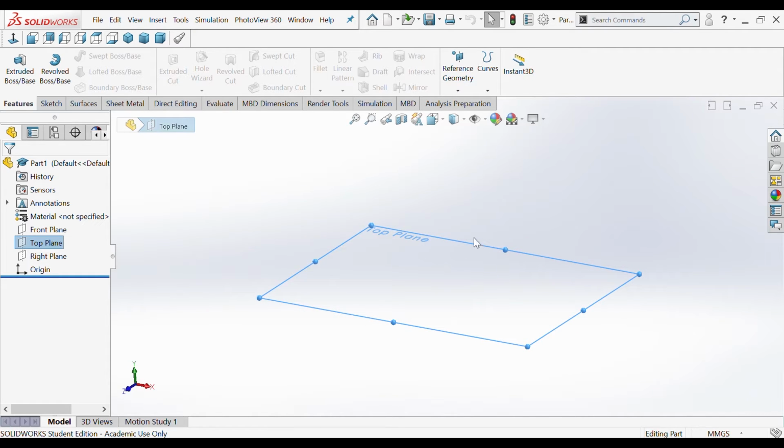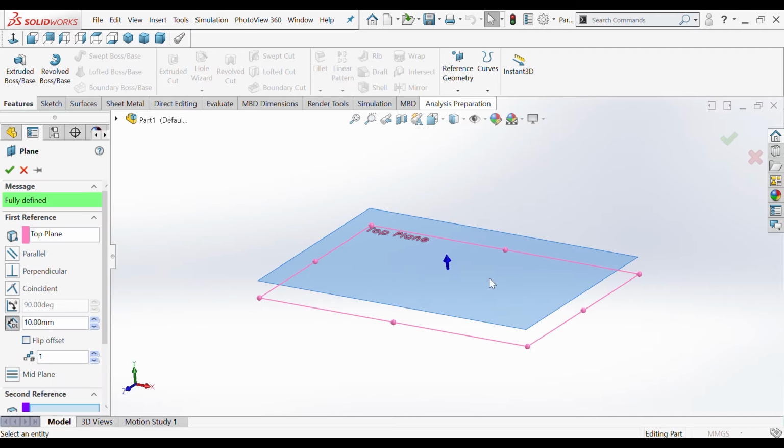planes. For you to create multiple planes, first of all, you can choose one of the default plane references from this Property Manager here. Then after clicking it, on your toolbar you can see the Reference Geometry option. Just click on this drop-down menu and select Plane. Once you select it, another plane will appear right here.